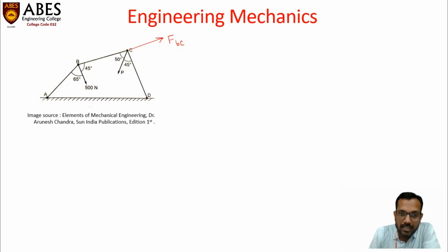Second force is transferred from point D towards point C. So we can show it like this because this member is also under compression. And it can be symbolized in this way, FDC. FDC is the force which is being transferred from point D towards point C. And each and every member we had already discussed here earlier is under compression.